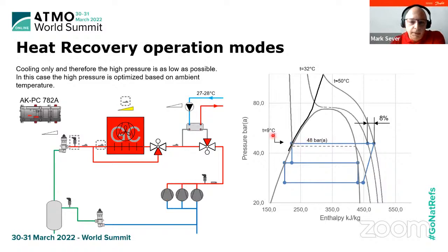And if we have a system where we have a water return temperature on the level of 27, 28 degrees Celsius, this will give us an idea how much we can recover from the system. And for that reason, I put here a line of the constant temperature of 32 degrees Celsius, so you can visually see what is the area we can use for the heat recovery.